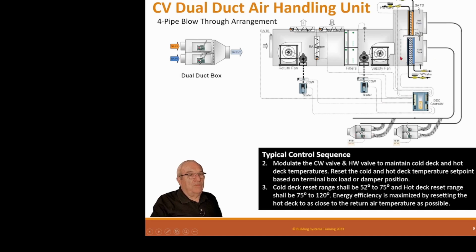So basically, when we started retro-commissioning some of these, we said, look, let's make this temperature set point the same as return air temperature as long as we can. That way we're using the heat of the lights, which used to be substantial. Not anymore, but used to be. Nowadays, it's plug load that's substantial, but we'd use that heat from the return to run this reheat, because we could actually reheat this room temperature.